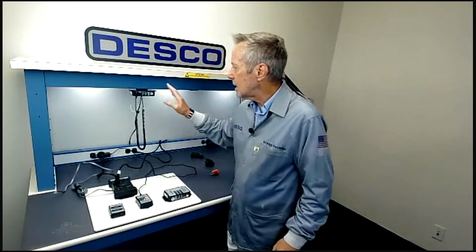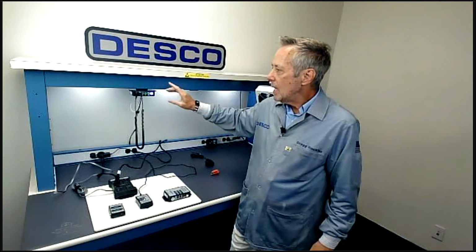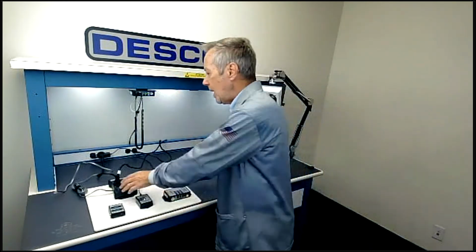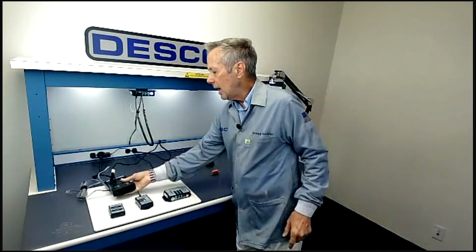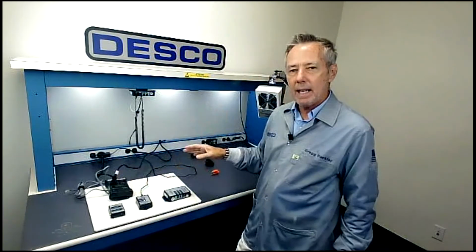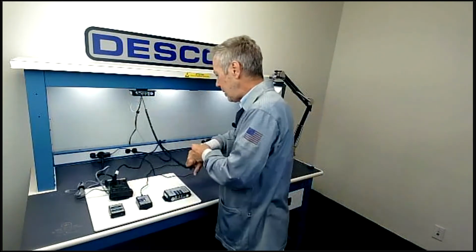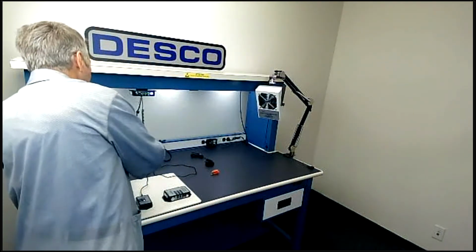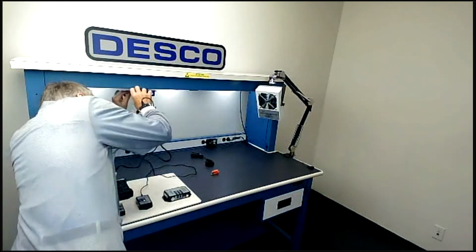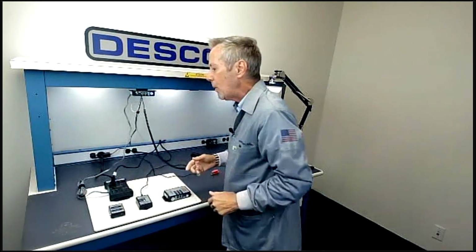Okay, now another feature that this particular monitor has, and with our new digital technology, we not only have the internal relay system, but we also sell an optional relay box, which you may be able to see down here. And this allows you to plug in AC powered tools or equipment and not allow those to be energized unless you're wearing your wrist strap. So I'm gonna put this back on. I don't have this connected, so I'm gonna reach behind and connect my wire. And this is fed by a telephone cable. So I'm gonna hook this up, turn on my relay box.